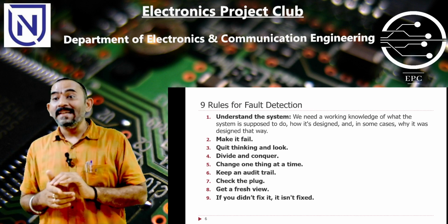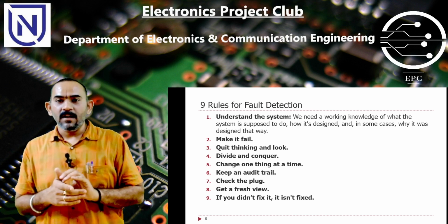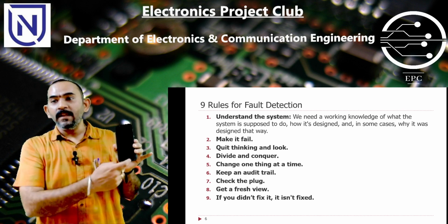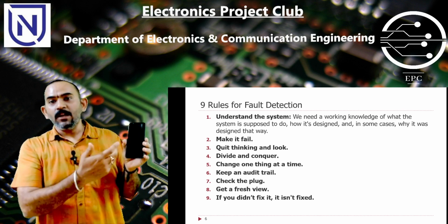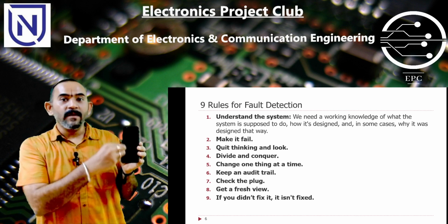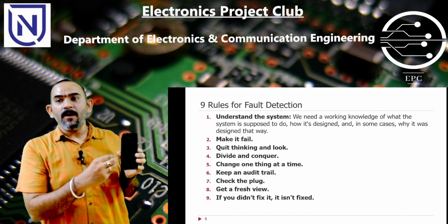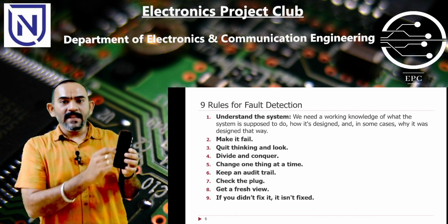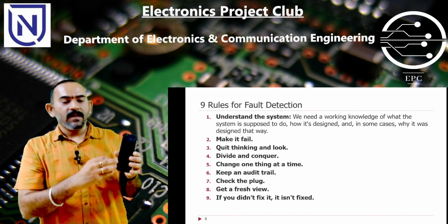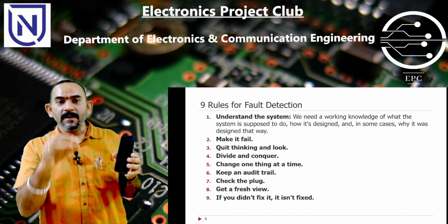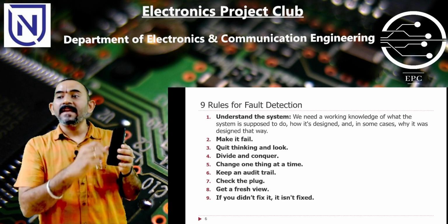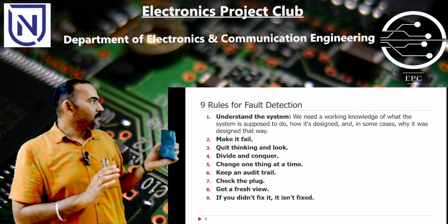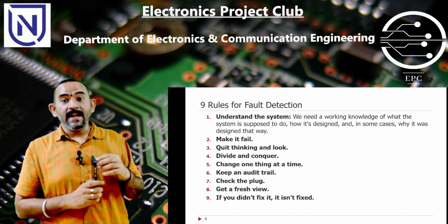The fourth one, divide and conquer. Coming back to the phone example, this phone has too many components, too many different blocks. If I try to pinpoint a fault by looking everywhere, it is not going to happen. So I need to first divide this into blocks and find out which block may have the problem. I have to divide part by part, make it into smaller chunks, and finally identify which location the fault is in. So this is what is meant by divide and conquer.